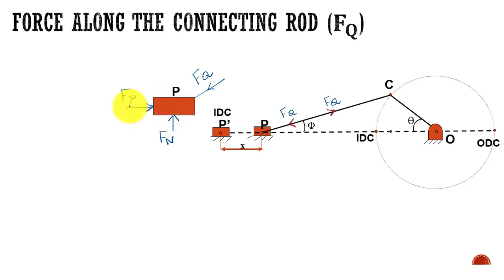So here, this is the piston effort. It is a net resultant force which is acting on the piston, and we know how to calculate this value. Fp is equal to Fl minus Fi minus F, the frictional resistance. In case of a vertical engine, we have to add the mass times the acceleration due to gravity, that is, the weight of the reciprocating parts also needs to be considered to find out the Fp value.